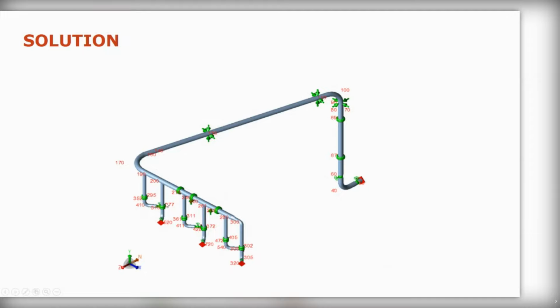Now what happens, see those legs dropping down? Those legs were in effect the absorbing legs. So they provided absorption to the expansion. Now the same, this straight bit of pipe still expanded the same way. We're still pushing into this corner. However, now there was a lot more flexibility in the system and the loads were within the allowable range, and that resolved the issues.